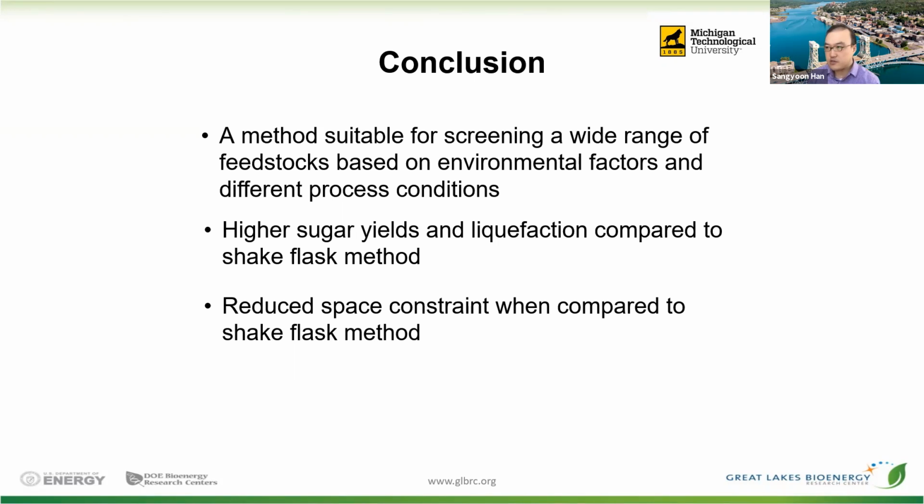Yeah, so a follow-up question: the main method you use is this roller-based method, and that is better than the shake flask method. I'm interested in why you think the roller method makes better fermentation and other types of biofuel synthesis. So the first and foremost reason is that in a shake flask method, the mixing is not happening properly.